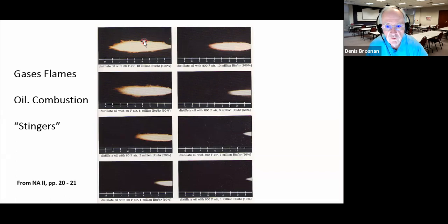Another thing to notice is the color of the flame. Very typical of oil flames to be yellow in color. What's happening here is that we are having unburned hydrocarbons, polymeric fuel fragments toward the center of the flame, and they are absorbing some of the energy that's being emitted during the combustion process. So this gives us a yellow light appearance in combustion.